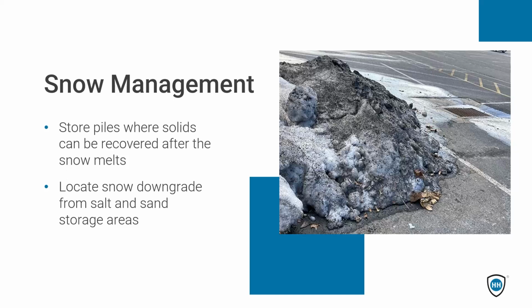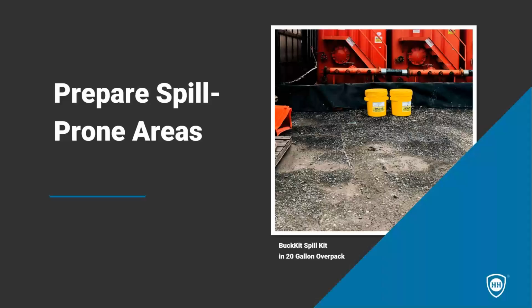So having a way to manage that and knowing where you're putting those piles can really help you to maintain the sediment that's in them and keep it out of your waterways, and also capture any trash that might be in there. So if it happens to pick up leaves or soda cups, whatever it may be, having your snow all in a dedicated area and making sure that area is well maintained, and especially after the snow does melt, will help you with keeping that out of drains and keeping that from polluting the environment.